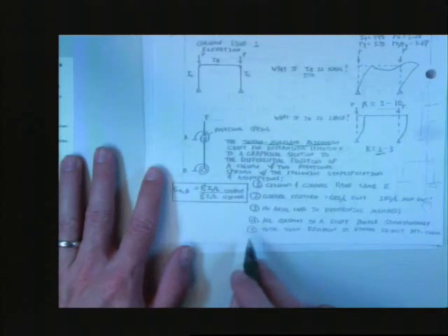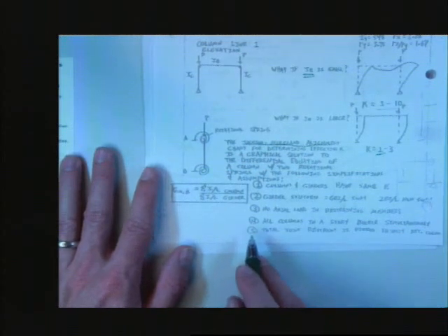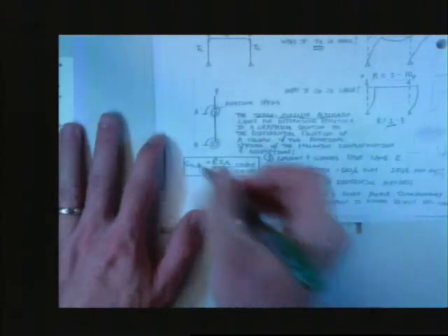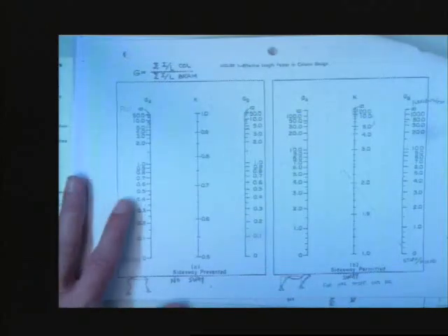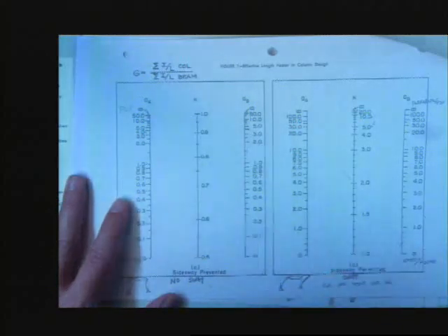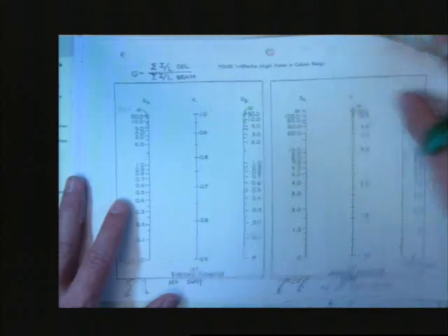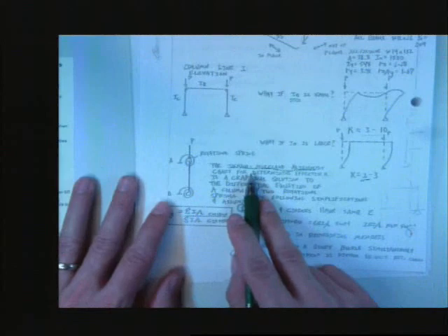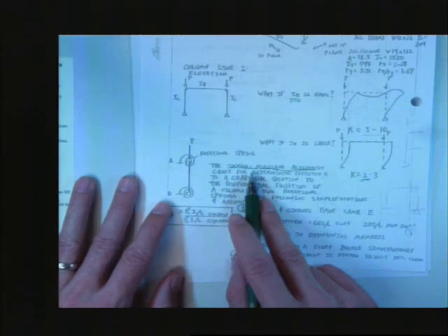They made 5 assumptions about the differential equation, and it went from solving a differential equation every time to, if I can do this for the top and do this for the bottom, then I can use this chart, and with the stroke of a pen, I can solve a 5-page differential equation. We all should send checks to their great-great-grandchildren, because they have really made our lives easier. Thank you, Jackson and Moreland. That'll be it for today.